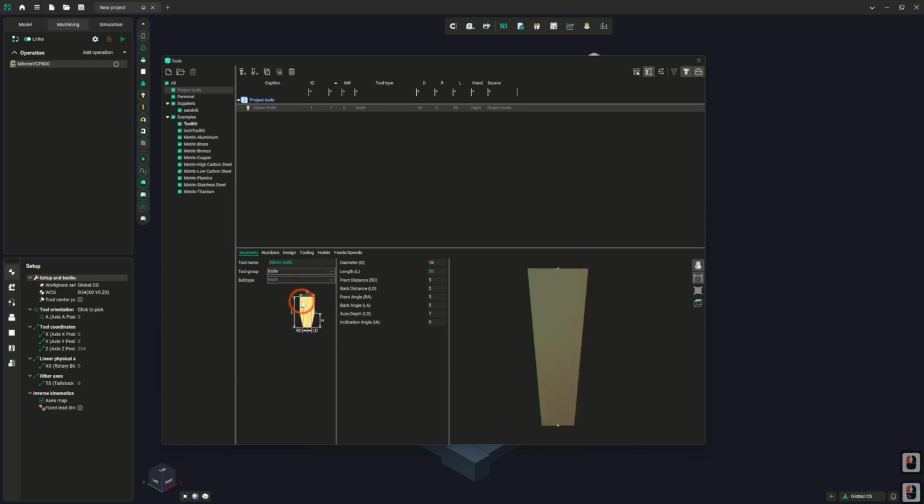We've also got capacity for dealing with drag knives. Now, these, if you don't know, are typically articulated tools that don't spin. They're just reliant on pressure, much like with, say, a vinyl cutter. As I say, drag knives are often used in things like etching and engraving, or in cutting thin, fairly flexible material that wouldn't survive rotary tooling very well. Often in soft plastics or fabrics, drag knives are used.